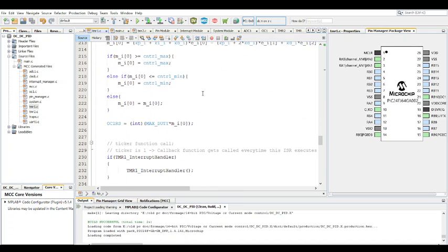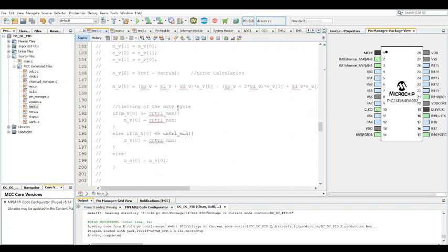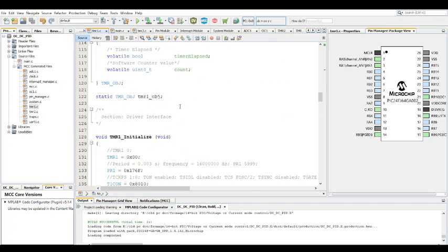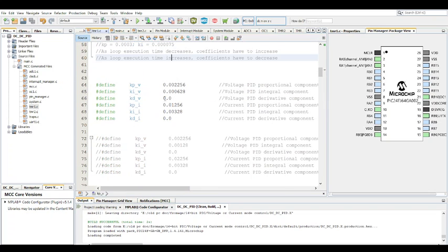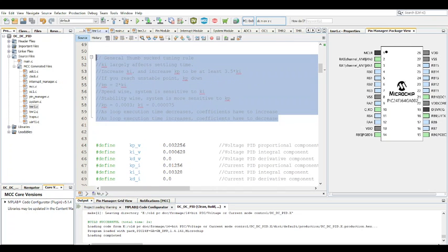Essentially the same. Let's say you were on another microcontroller architecture and you were using 3 milliseconds. You could literally use these exact coefficients. Obviously, if your loop execution time or timer interrupt time is lower than that, you might have to increase these slightly, or leave them as they are and follow the normal rules.